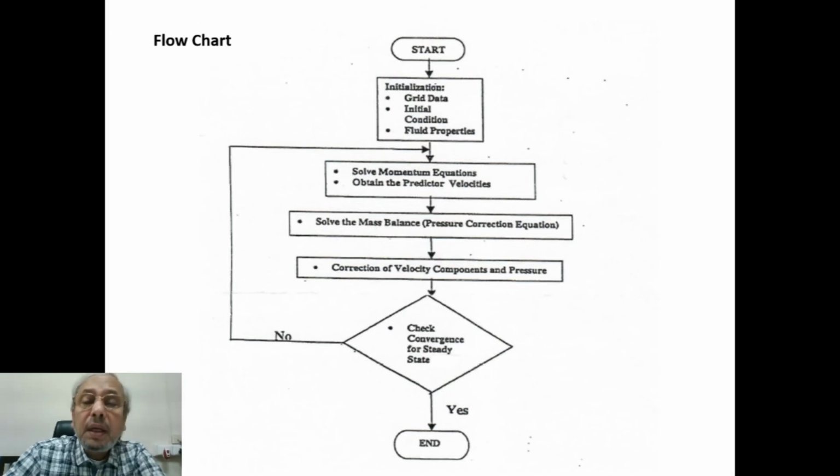Now I will briefly discuss the flowchart. As you can see, grid has to be generated for meshing the geometry of interest, and all XYZ locations of all the points will finally describe hexahedrals of various sizes and shapes.